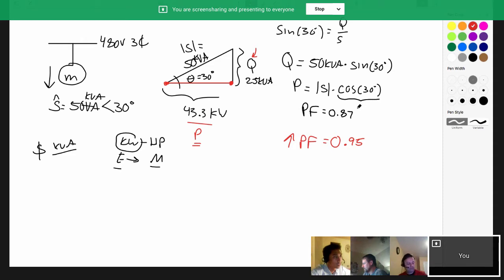S divided by P, sure. So we said, okay, power factor equals, is it S divided by P or P divided by S? Oh, P divided by S, sorry. Perfect, no problem. And remember, the easy way to remember, we know power factor is a decimal, right? We know it can never be bigger than 1. And we know that S is always going to be bigger than P, unless it's equal to it. So we know we've got to put the bigger number on the bottom.